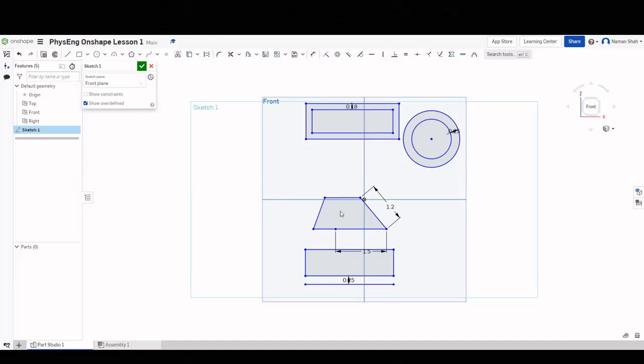I'm going to go ahead and delete this angle just to show you what the vertical tool looks like. So the vertical tool is much like the horizontal tool, and it'll take whatever line you have and make it vertical according to the plane that you're drawing it on. So let's say we click this line here, and boom, it's perfectly vertical. And those are all of the tools that you will be needing for this lesson. Like I've said multiple times before, there are many, many other tools that are also very useful, but for our purposes right now, those are the only tools you're going to need.